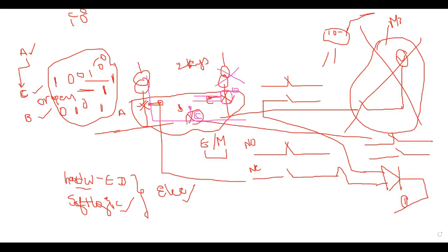So mechanical interlocking, electrical interlocking. As this is a low voltage system, a 415 volts distribution, mostly we prefer mechanical interlocking. Or at maximum, up to some extent, we will go for hardware electrical interlocking. Soft logics will not be required because it's a low voltage system. If you want to develop a soft logic, again, you have to purchase some intelligent electronic device, which we will call a BCPU or some controller kind of thing. It costs more.